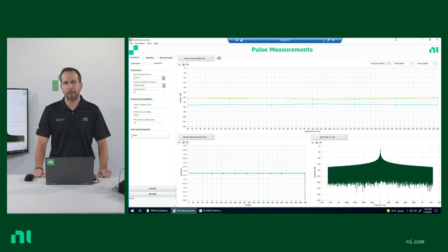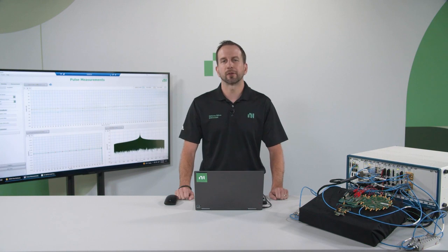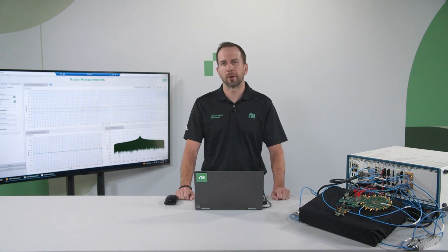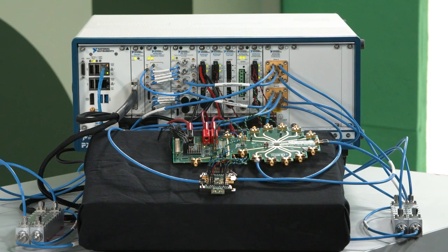We will perform not only pulse profile measurements, but the pulse-to-pulse stability measurement itself simultaneously using the vector signal transceiver, or VST. As per all of the interactive examples within the library, you are provided the ability to both configure the hardware as well as the stimulus and measurement, as well as in real time view the measured results for interactive analysis. In this particular case, we're using the vector signal transceiver in a shared LO configuration. This allows us to optimize out the phase noise impact of the instrumentation itself, and therefore tackle one of the key challenges of these measurements.